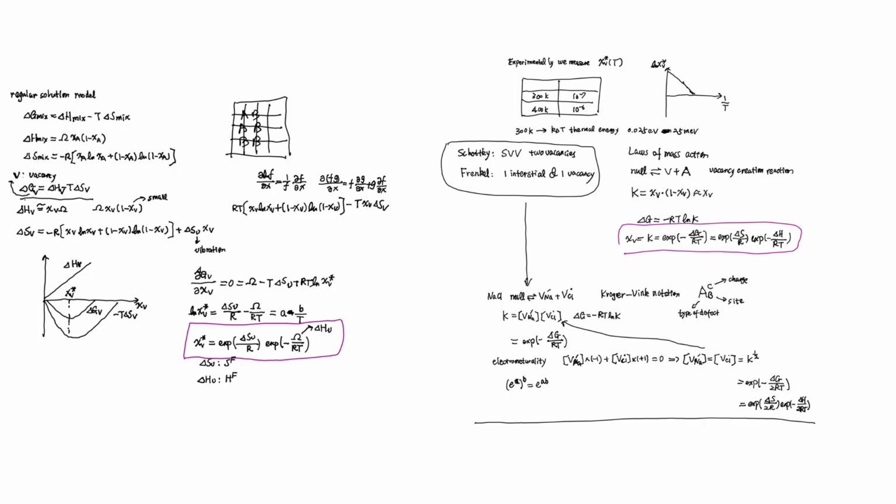On the other hand, for the 4 eV here for tungsten, people consider this a very high formation energy. It's very difficult to form a vacancy in tungsten, not just because it has a high melting temperature, but simply because the bond is so strong.